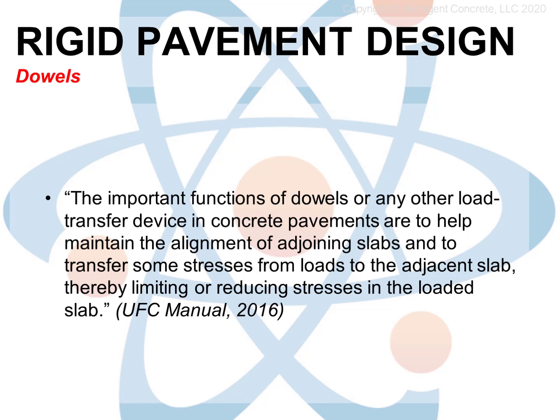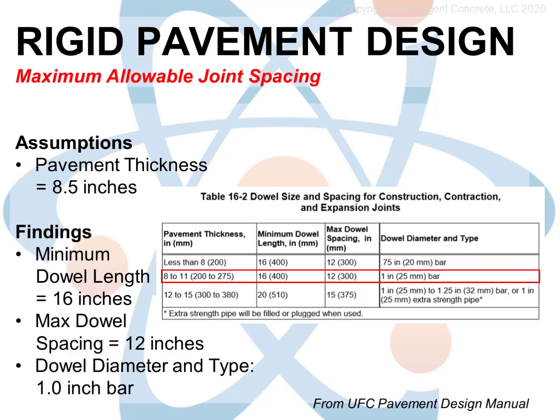When they get over a 1/2 inch, vehicle speed and control are affected. California's Highway 99 between Bakersfield and Fresno had drops of more than an inch before renovations were performed. Fortunately, we don't have to work too hard to figure out the dowels. Through a combination of scientific analysis and practical experience, we have available tables that help us with dowel selection.